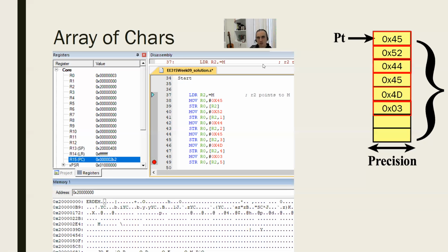Okay, so regarding your question, LDR reads from the memory to the registers, STR from the registers to the memory. Clear? Okay, because you said LDR. And yes, STR is 32 bits, STRH is 16 bits, STRB is 8 bits. Answer to your question? Okay, these things get confused, I know. They are very fundamental and simple, but it takes a bit of your time not to confuse them and do them, I mean, naturally. It takes time before it becomes natural for you guys.